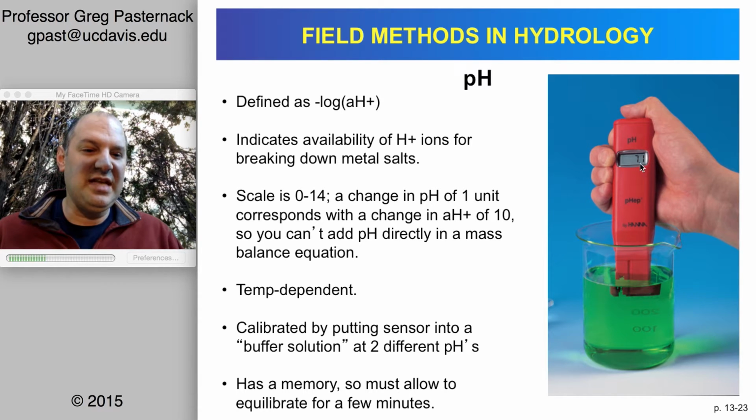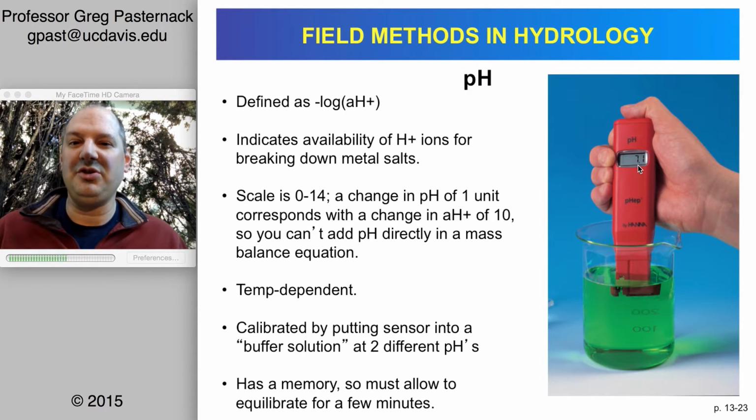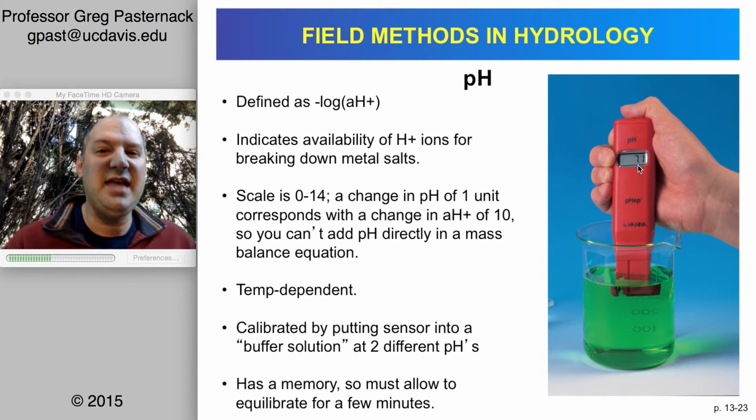So with these pH sensors like you see in this photo, you do a calibration on the fly. This could be done the day before or the day of your field measurements. Of course, it's measuring a voltage, but what you do is you put it in one solution that may be like a pH 4, and you record it, let it equilibrate, and so now it knows what's the voltage associated with that pH. Now you take it and put it in another solution like a pH 7.